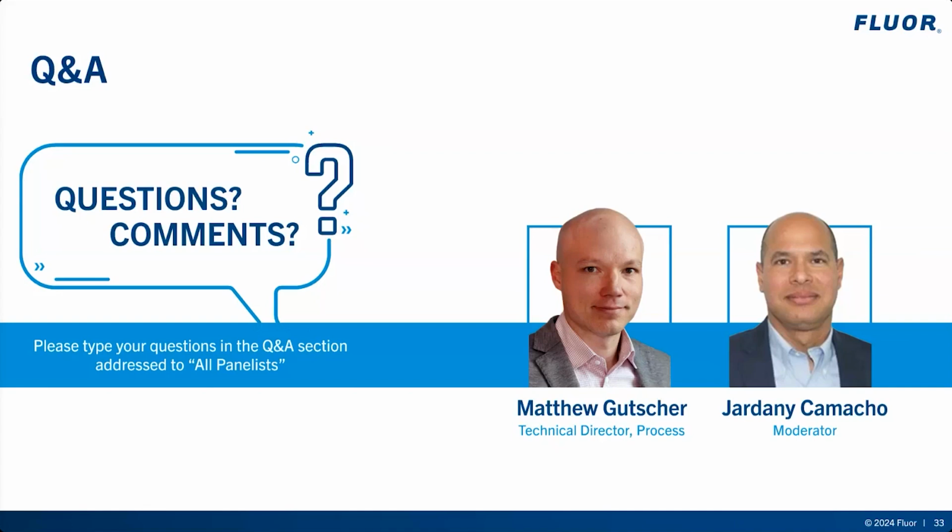One more question. Can you expand on any differences in project considerations associated with CO2 utilization applications? I think there's two items worth highlighting. CO2 utilization projects have additional processing steps to convert the CO2 into a final product. And this will likely have implications on the quality of the CO2 product produced, or required, I should say, when compared to CO2 being sent for sequestration, as well as the fact that there are downstream processes that should present additional opportunities for facility integration, including heat integration.